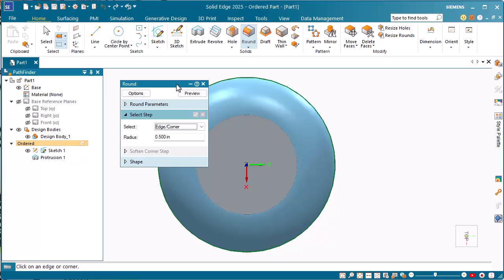So Solid Edge has given us the option of using what they call the vertical command bar. And the vertical command bar has more text in it, and it's set up much more like the Solidworks property manager. You step down through these steps one by one. If something's grayed out, it means that there's some sort of prerequisite that's not satisfied, or you don't have the right things selected, or something like this.